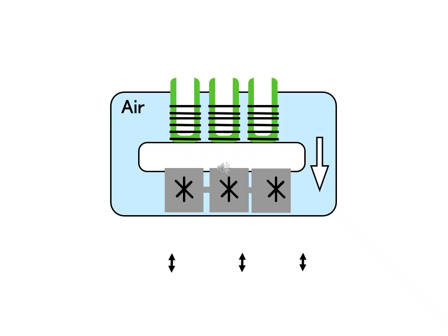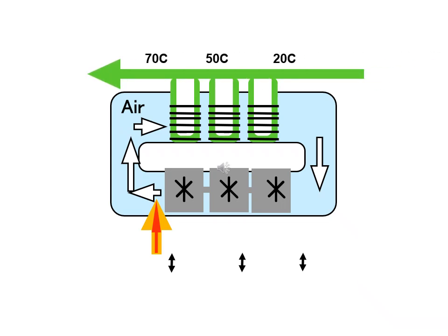In the evaporation area at the bottom of the figure, warm seawater, shown in brown, enters this area, splashing into small droplets inside the evaporator and cooling down through latent heat of evaporation. The generated high-temperature steam enters from the left, releasing energy during condensation and heats the circulating water indicated by the green arrows. In this way, latent heat is stored in the pure water.